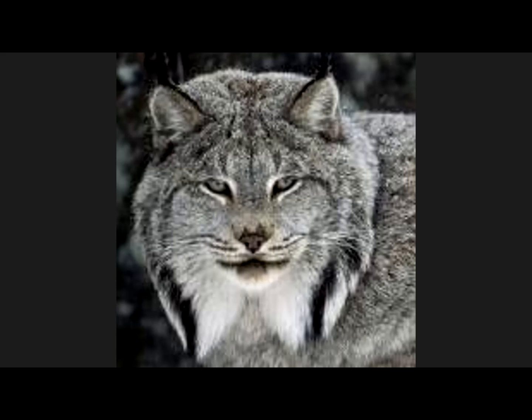Yeah. There are different ways you can compose the data. It's easiest maybe to use Spin to make your lookup table, and then turn the streamer on. Oh, but you know what? Here's the thing. You have to run the streamer in another cog for that kind of application, because it wants to use the LUT, and the Spin interpreter uses the LUT, right? So that's why you'd want to, and why I did in this case, launch it. Well, no, actually, when that thing took over, it just wiped out the Spin that was going in the background, and it took control of the cog. But if you want a real application, you probably want to start up a cog and have it run some assembly language to operate that streamer, and totally use the LUT, which you can't use if you're using Spin.